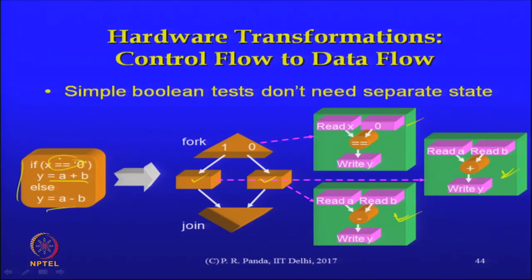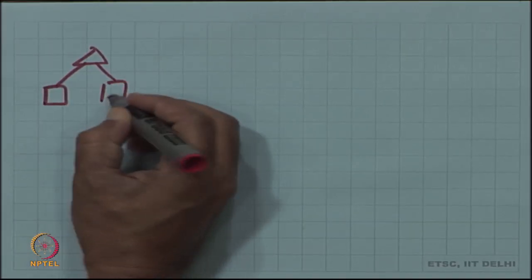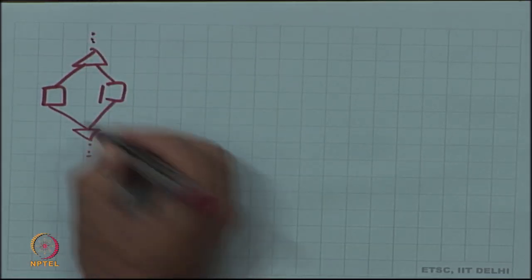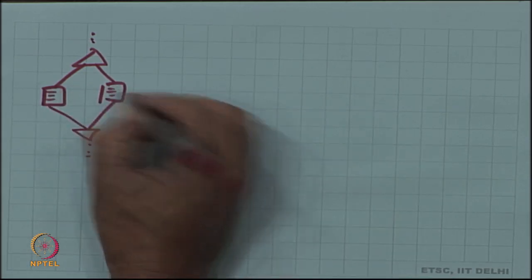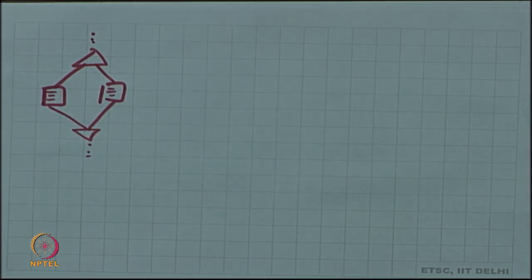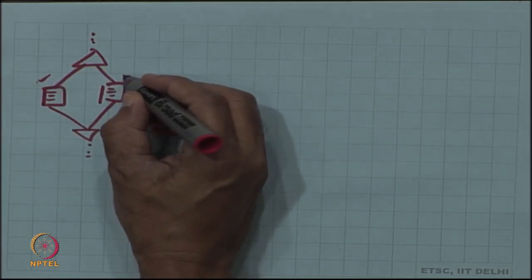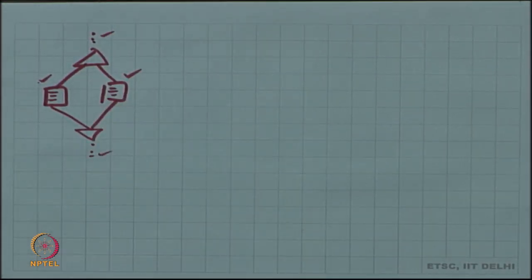And the most straightforward way to take it to the next level of synthesis is that you schedule one basic block at a time. So, that you have from an if statement like that, this could in general be several clock cycles in length. And what would the overall strategy be? We schedule each of the, we schedule this basic block separately, this one separately, and so on.